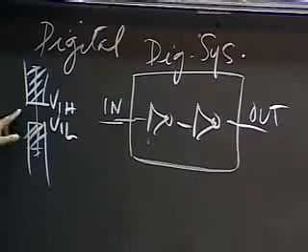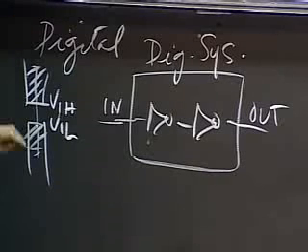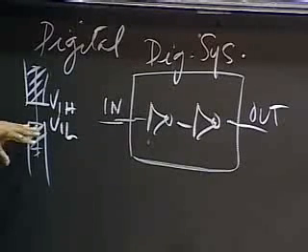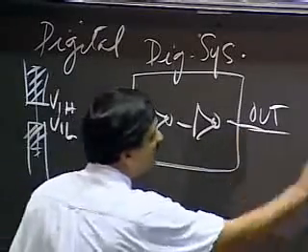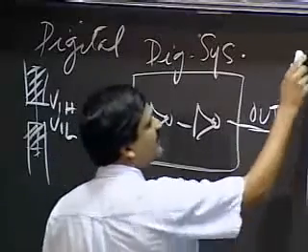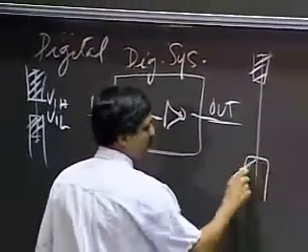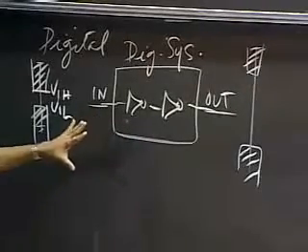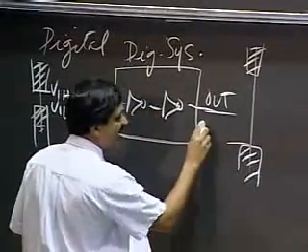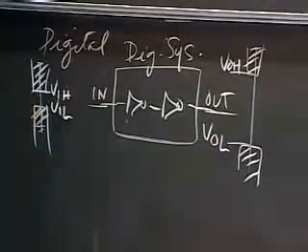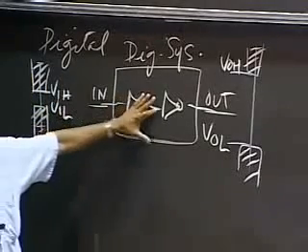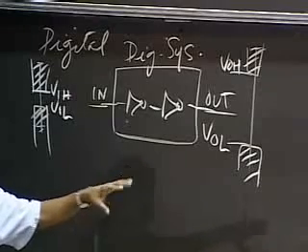We said that this circuit must recognize signals that are higher than VIH, 3 volts for example, as a 1, and simultaneously, any signal that has a voltage level less than VIL, say 2 volts, should be recognized as a 0. Okay, that was the input constraint. On the output, it had a similar set of constraints, where we had tougher constraints on devices, where we said that the output had to satisfy an output low constraint and an output high constraint.